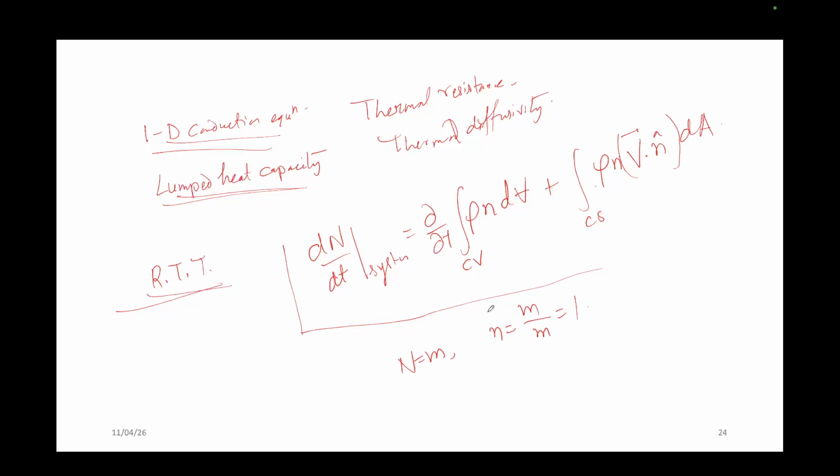Next is boiling and condensation, and what is the difference between dropwise and film condensation. A derivation is there for the condensation. Please look into this. What is the main difference required in boiling? See the Leidenfrost point, the Nukiyama experiment, and why the Nukiyama experiment is not able to find the transition boiling curve, and all these things. Please look at the basic concept.